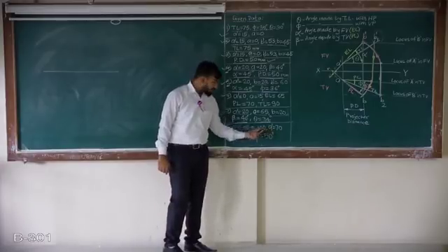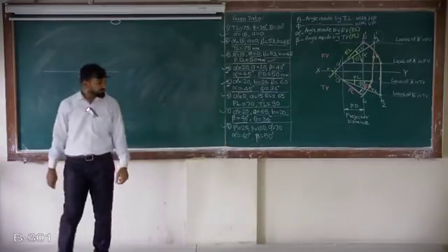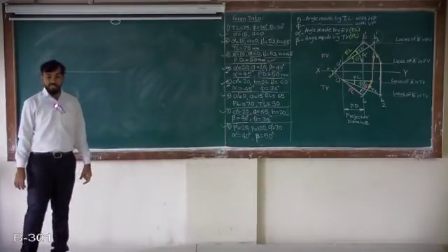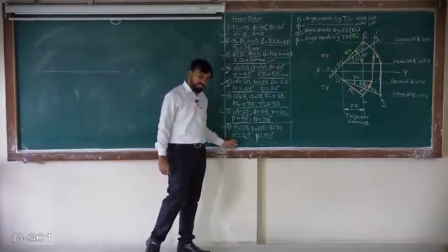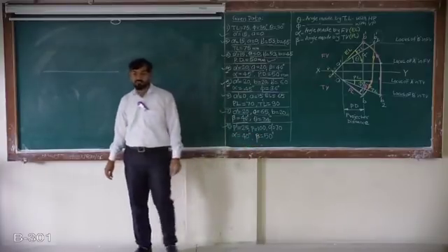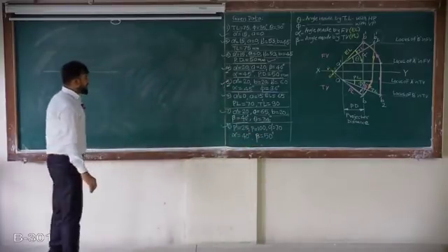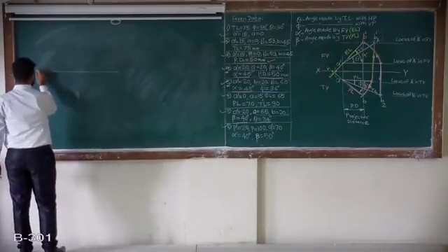Point Q is 70 mm above HP. Front view and the top view makes an angle 40 and 50 degree respectively, or it may be the last sentence for this as elevation makes this angle and plan make this angle, that is alpha and beta. So I am going to solve this problem by just plotting given data.